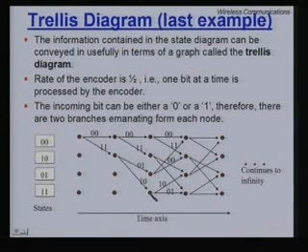So, you will go to state 0 1, but what is written on the branch tells you, after the logic, what is output. So, in the process, if I were sitting on 1 1 and a 0 comes in, I would go up to 0 1, but what will be thrown out of the encoder is 1 0. On the other hand, if I am sitting at 1 1 and another 1 comes in, my state transition will not happen, but I will shoot off something different.